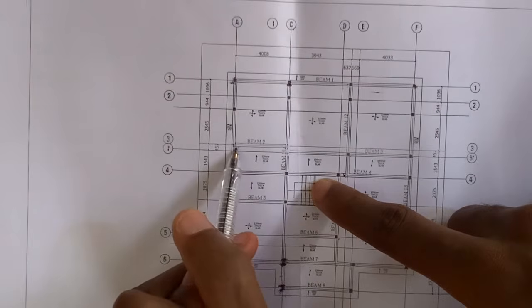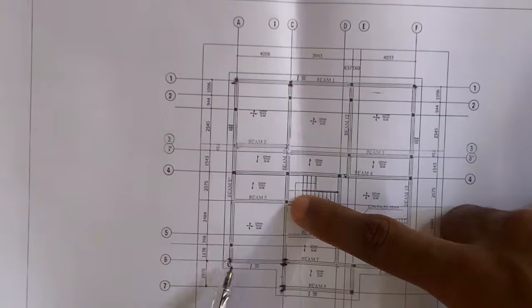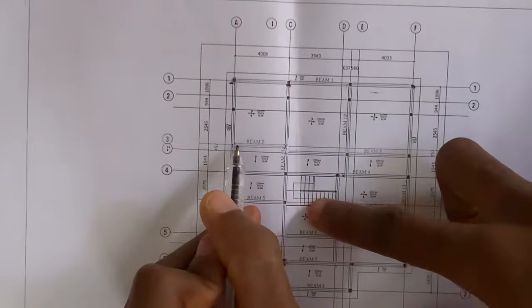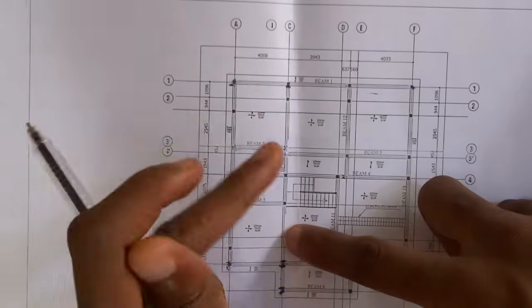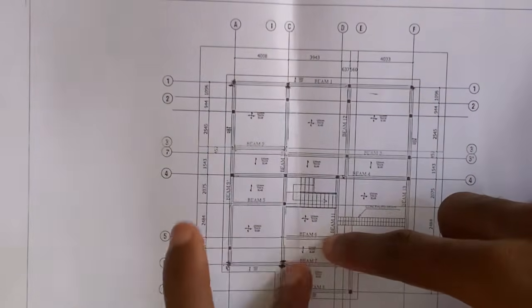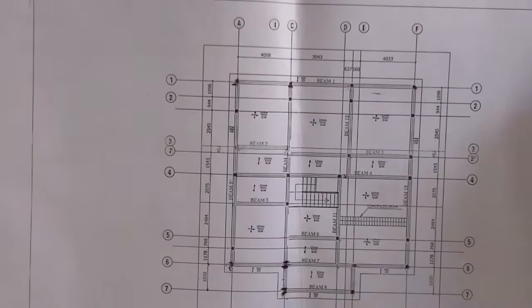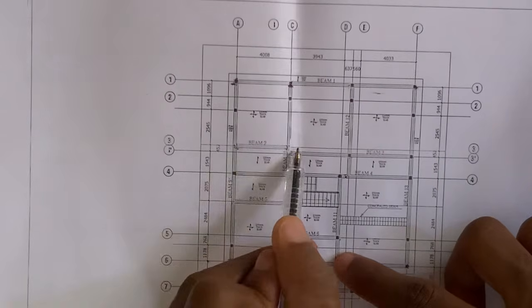I hope that makes sense, because we cannot take this one to be out to out, because we've already measured this one here and we measured this one here. If you measure this one to be out to out, then we've over measured. That is why we are making this one in to in. I hope that makes sense. Now beam 2 is intersecting it, so we'll have to remove that point of intersection. That point of intersection will be over measurement. So when we remove it, we're going to be removing half of the thickness of this beam or this wall, which is 230, half of 230 from both sides.